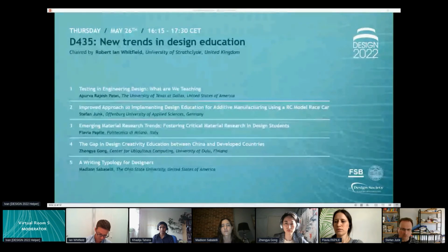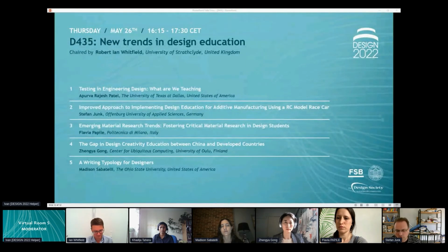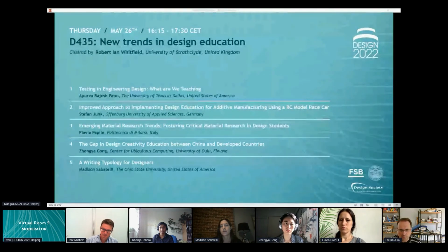Yes, you can see that you're right. Also, our students, I can recognize that many of them already have their own 3D printer at home, and they use it for small projects. But I think if you have a closer look at the product development of more complex products, they should know more than only one method, like, for example, the fused deposition method, which is normally used for home printing. They should also know something about multi-material printing, for example, and they should also recognize that when they design a part they have to consider material properties, which could differ for different parts in one product.